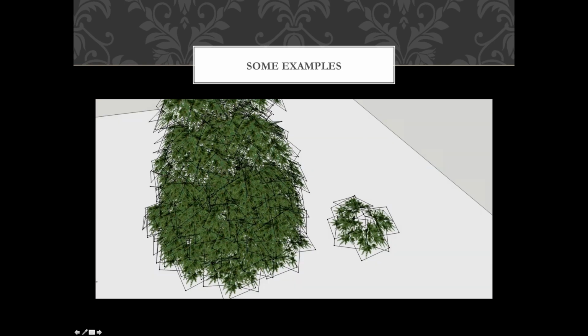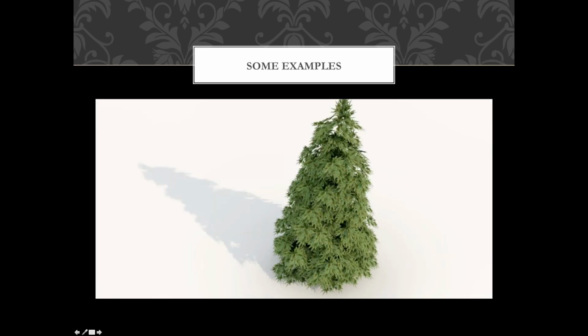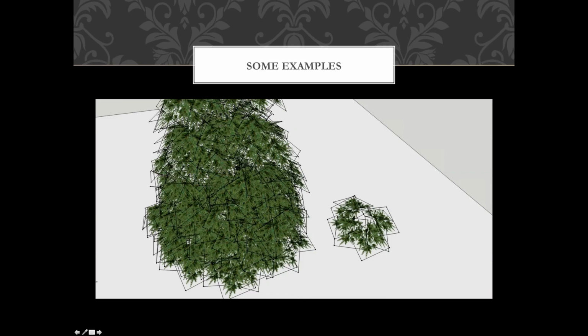And here's what I was talking about earlier when you don't have to clean up stray lines. This is just a PNG I did in Photoshop and imported into SketchUp, and they're transparent edges, and then this is the edge of my component here, and I stacked them into this tree here. So then in Podium, when I render, all of those stray lines disappear, and all you see are the colored surfaces in the middle here.